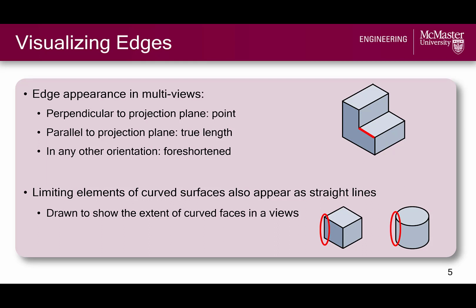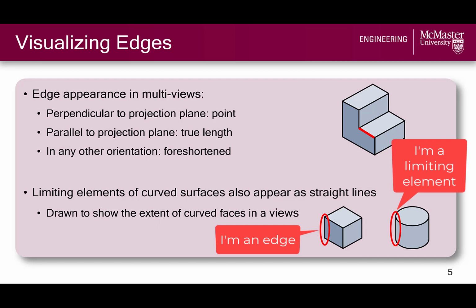But recall that straight lines can also represent the limiting elements of curved surfaces. So it's important to cross-reference other views to determine whether you're looking at an edge or a limiting element of a curved surface, as we saw with the last example in the previous lecture video.